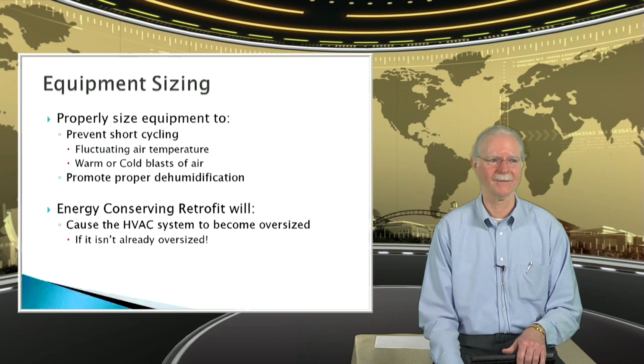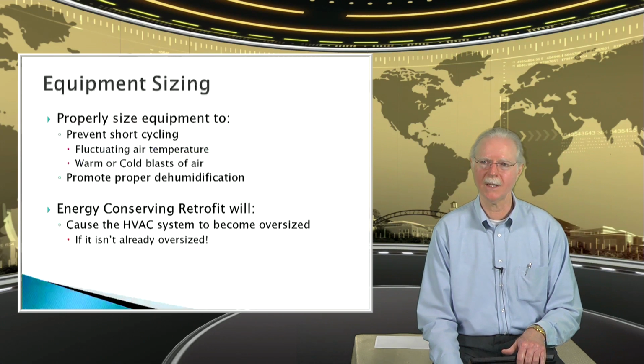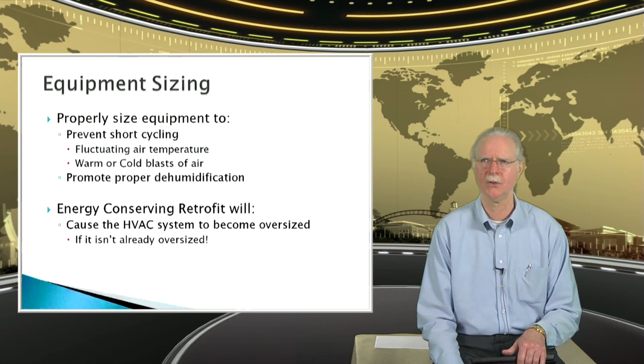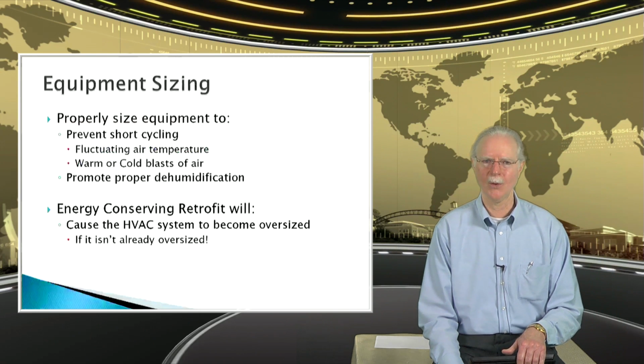That's what happens in real life. So now we put in this piece of heating or cooling equipment that's over-designed, and what happens? Well, the first thing that happens to us is something we call short cycling. The equipment turns on. It takes a minute and a half to heat or cool the place. Then it takes another 2 hours before it calls for heating or cooling again. That short cycling process means that the equipment did not get an opportunity to ever operate at its most efficient.